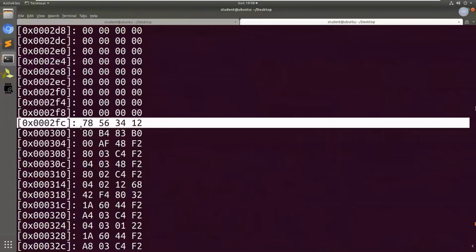So even though this device is secure, even though the actual physical contents of flash have the correct value, at the moment of time at which it booted, by playing with the voltage and ensuring that the system booted in an unstable state, what we did is we made sure that the single read where it checks that value in the boot ROM, it read something else. So what might it have read from the flash? Well, maybe it read 0, 2, 3, 4, 5, 6, 7, 8, something like that. Maybe it corrupted the 8.